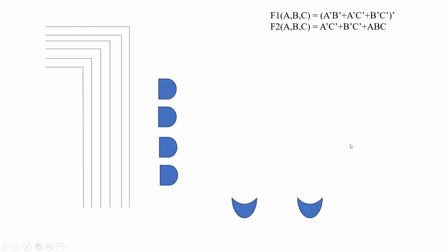So now we are going to implement these two functions. Already we got the proper number of product terms; that requirement was 4. First we have the input side, so again we have to use a buffer. We have 3 inputs, so we are going to use 3 buffers here. This one is connected here, and this input is A for us.